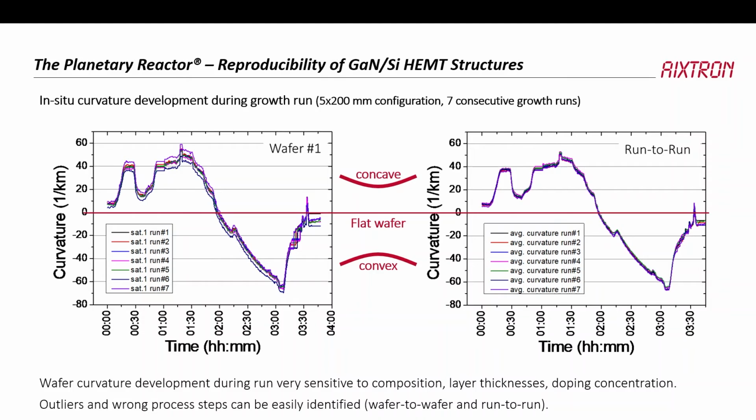We measured the curvature using a laser curvature measurement tool, which projects 3 spots onto the surface. The reflected laser spots are then read out by a CCD camera. From the relative positions of those spots in the reflection, you can determine the curvature in 2 dimensions, because you have a triangle of spots that you project on the surface.